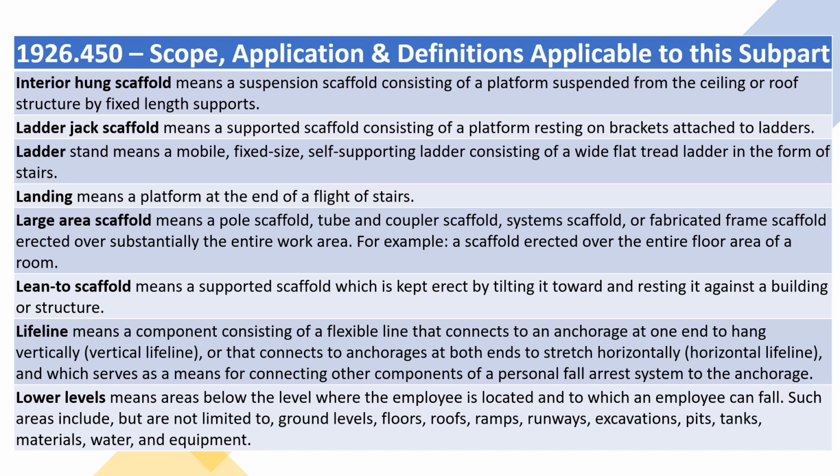Lean-to scaffold means a supported scaffold which is kept erect by tilting it toward and resting it against a building or structure. Lifeline means a component consisting of a flexible line that connects to an anchorage at one end to hang vertically (vertical lifeline), or that connects to anchorages at both ends to stretch horizontally (horizontal lifeline), and which serves as a means for connecting other components of a personal fall arrest system to the anchorage.